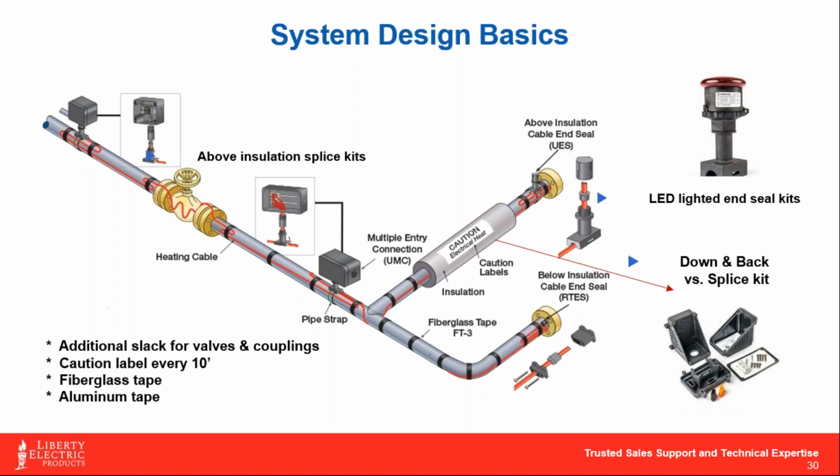But oftentimes an extra 15 feet of heat cable is a much better investment versus trying to pull off an acceptable splice plus the splice box and everything that goes into that. I say that with a little bit of bias, because you need to know in some respects, you don't ever put a double run, even if you're low temp self-regulating cable, on, say, a plastic PVC pipe. If it's a metal-based pipe, you can do that, and that's no big deal.